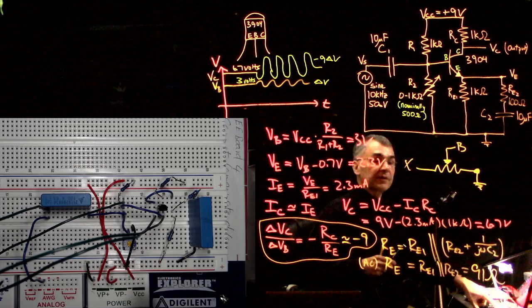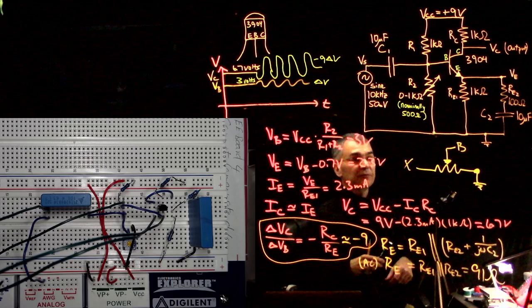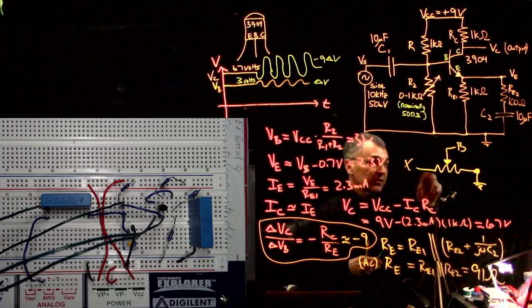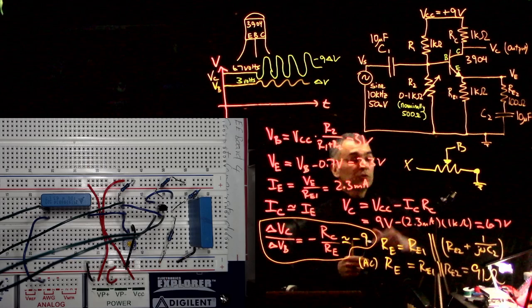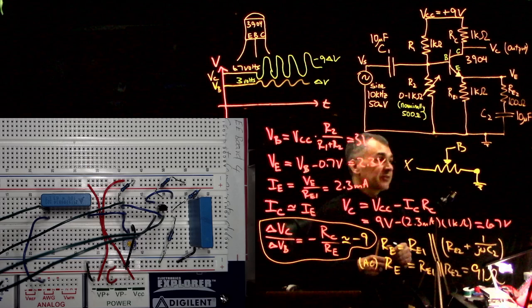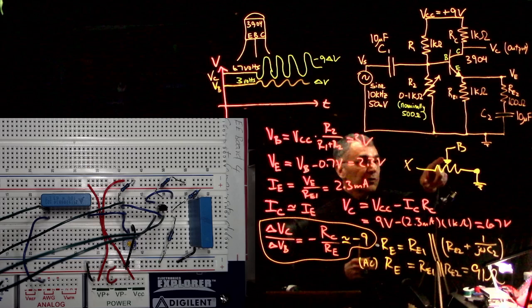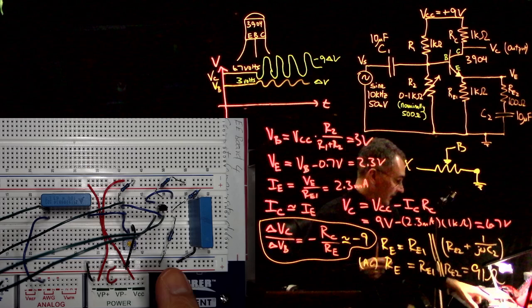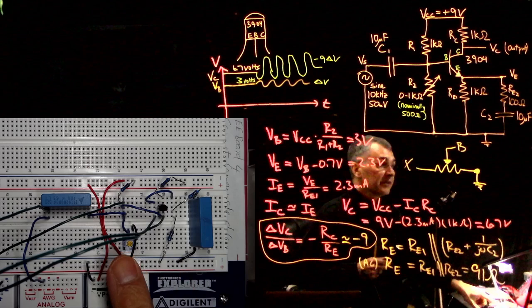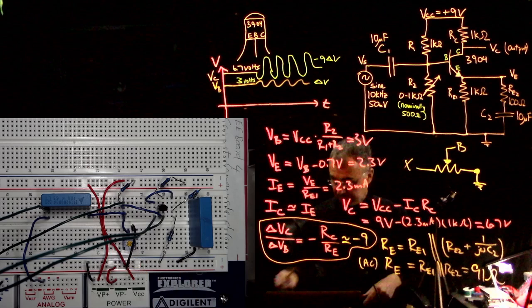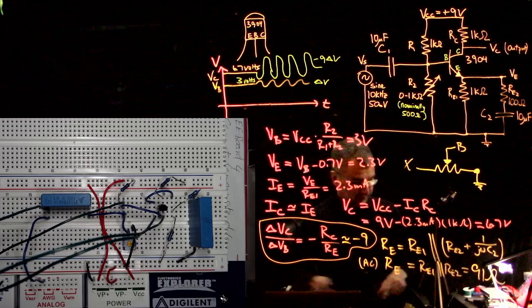So anyway, fine. You're going to see me turn the screwdriver to the right later to increase R2, and I'll turn it to the left to decrease R2. But this is how I connected it. So the middle, the wiper, goes to the base, and then this little black wire goes from the right-hand side of the potentiometer down to ground. All right.